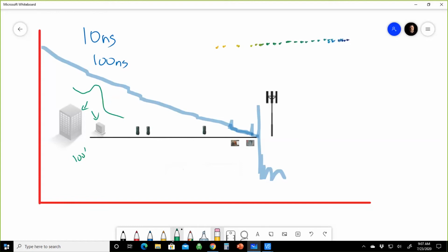be able to pull it apart. And so that's why when you're doing fiber characterization, you do a front panel shot, and then you do a short shot, they call it, and a span shot, right? Those are the two big things that we do. And so 100 nanoseconds merges those two together. It might merge these two together into one big loss, but it will see all the way to the end.